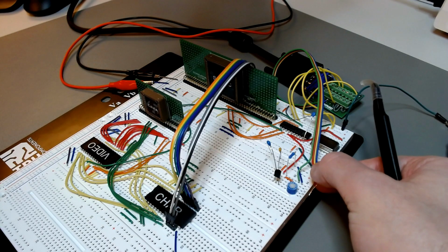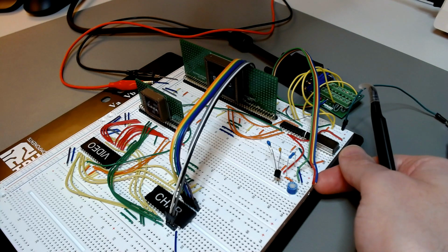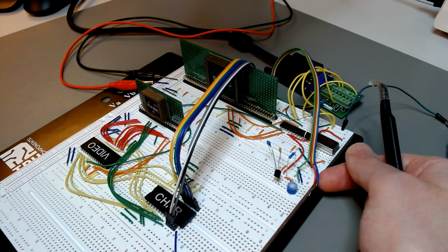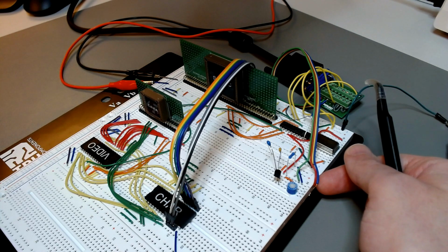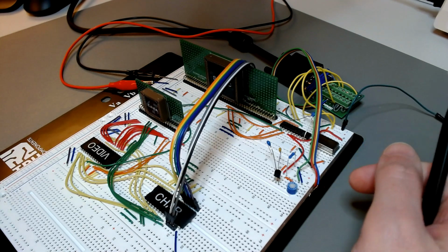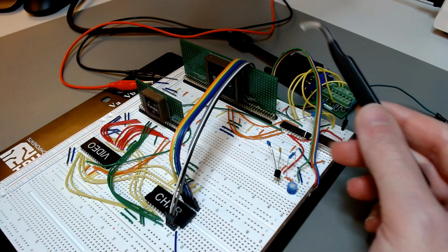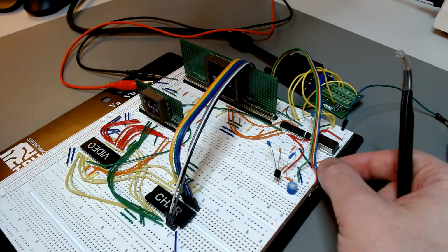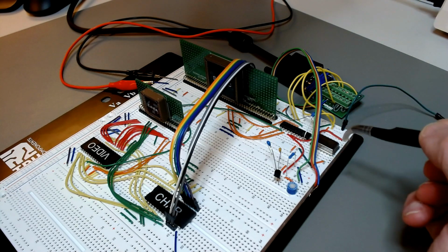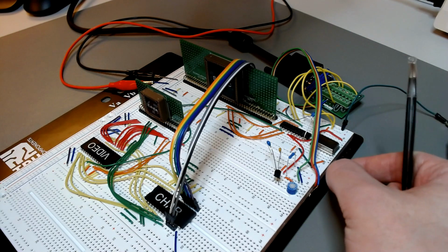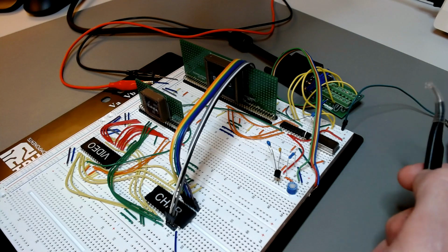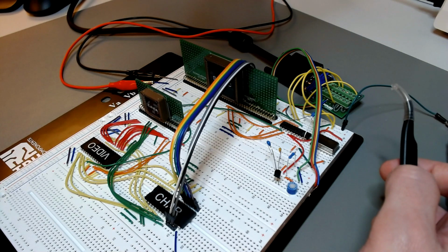Now blue and red are not connected. I found that I get a better, sharper image if I don't connect these at all, even better if I don't ground them at all, because there's some circuitry in the television that detects when there's no signal there, and then the equivalent circuitry in the TV probably is just shut down, and we get a sharper image that way. This is pretty much it, and it's working pretty nicely.